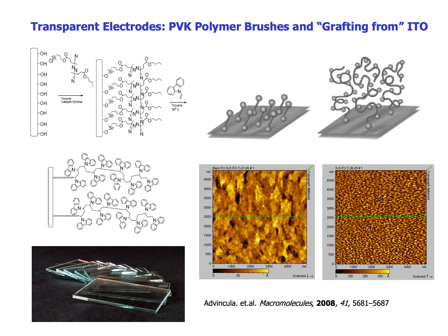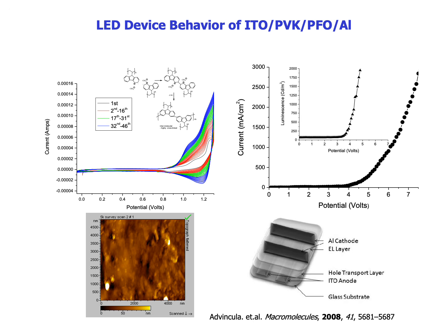The result is a homogeneous film as shown by the AFM micrograph, where the smooth film serves as a hole transport material to complete a device. And so we demonstrated a similar configuration as the previous device. In this case, a PVK brush that was cross-linked electrochemically produced a lower turn-on voltage as shown here compared to